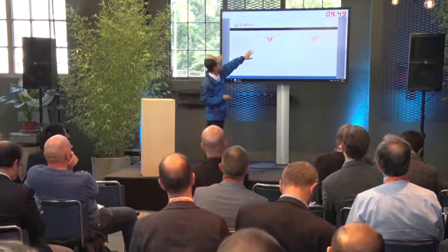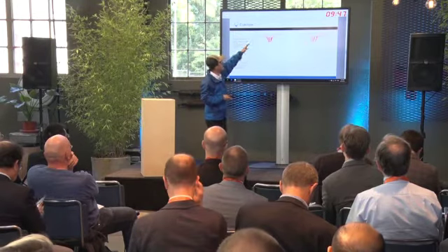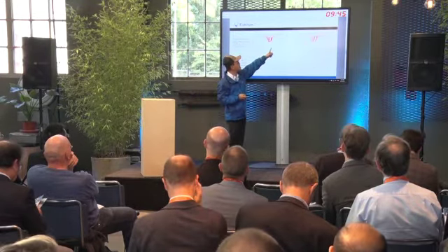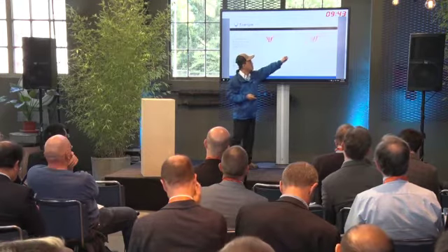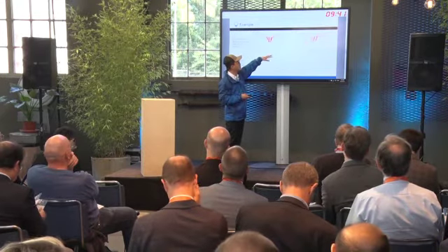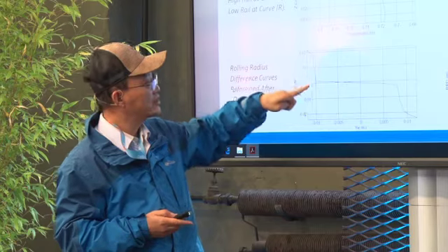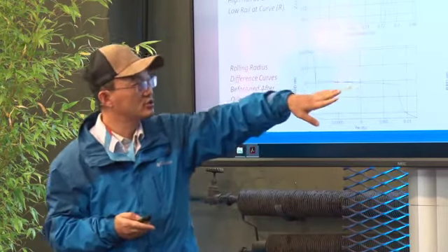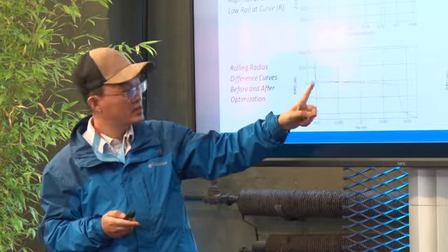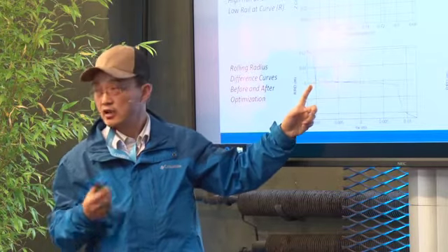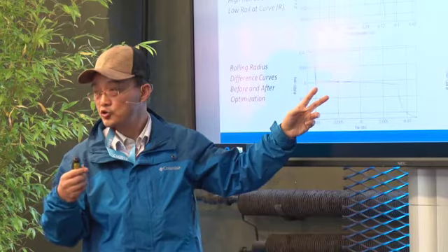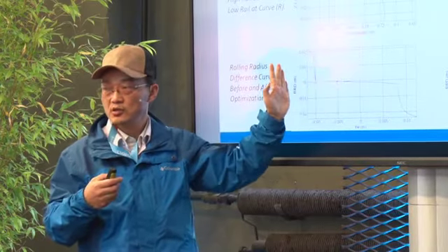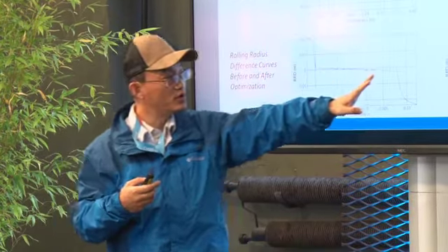Now here is an example of the calculation. This is the actual measured wheel and rail. This is the high rail, this is the low rail, and this is the contact condition. We can find by this RRDF that this contact is not good, because there is a small rolling contact radius difference on curves when the wheelset moves. So we can modify that.